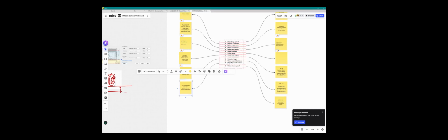The one thing I would tell you to remember is that model line acts as an object. So what that means is that if you draw a model line on the ground floor and then you have a roof over the model line, you're not going to see it, because the model line is below the roof. On the other hand, a detail line will always show above whatever you're drawing. All right, guys?